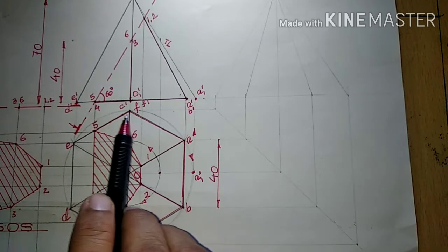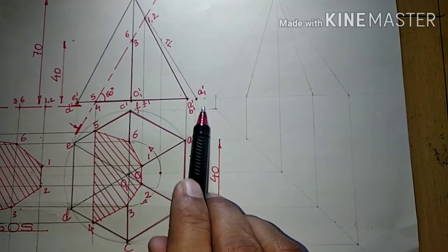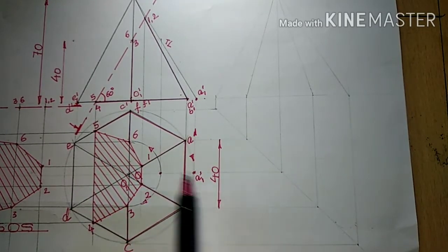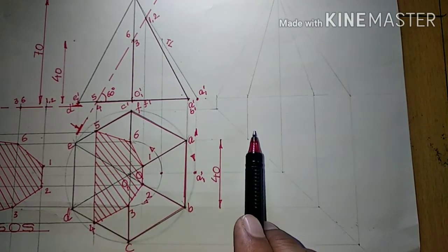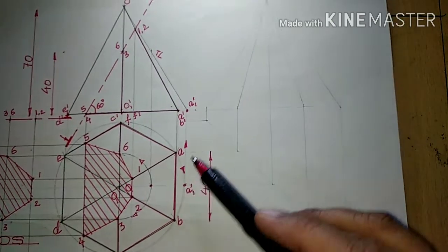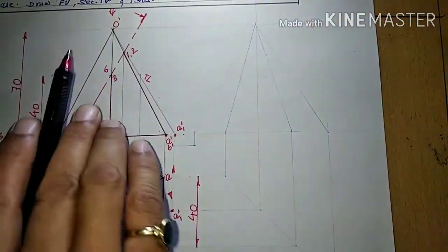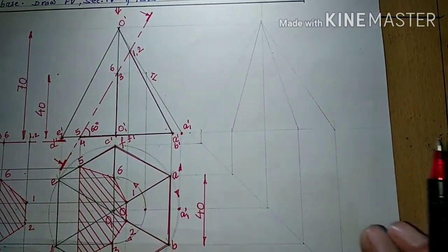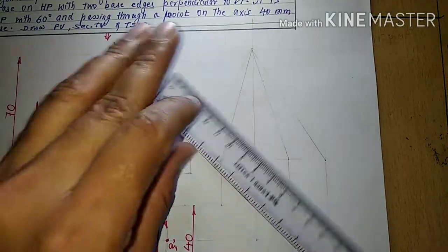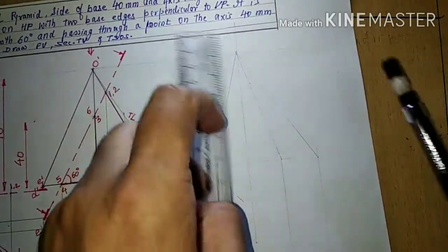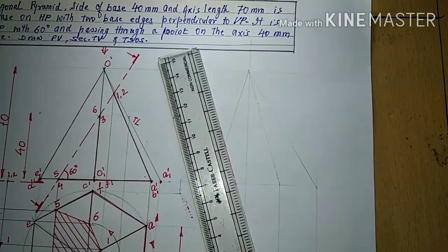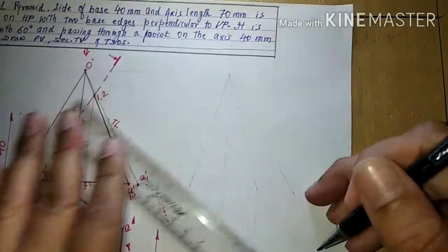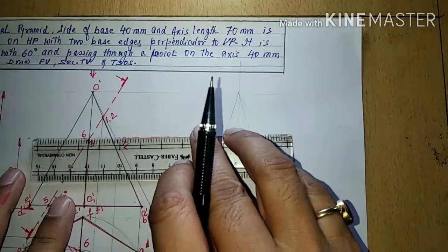We simply take all the points here. We draw a 45-degree line. We'll take all the positions along this 45-degree line, in upward direction. Similarly, from front view, we'll take all the positions on the right hand side and we'll draw our front side view now. So we'll just transfer all the points first.